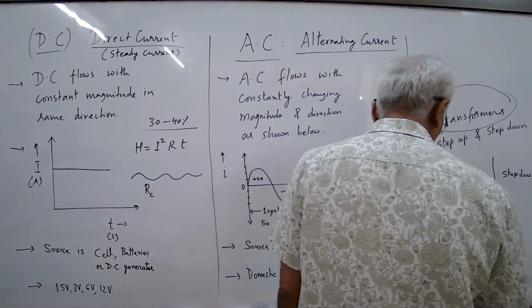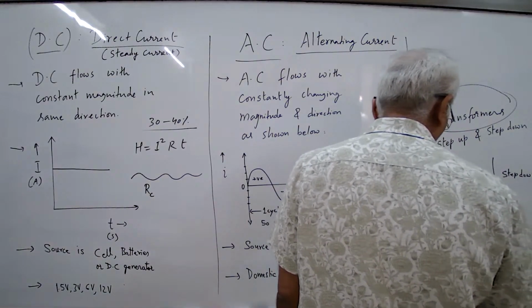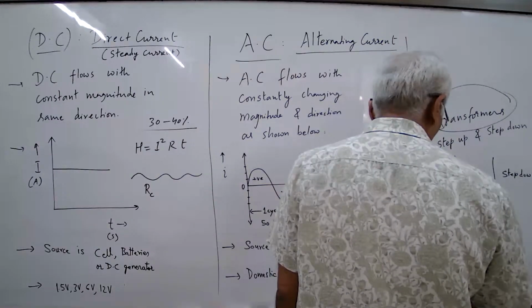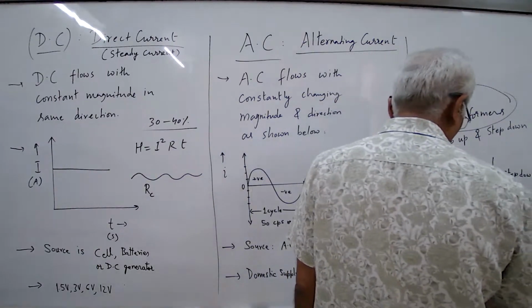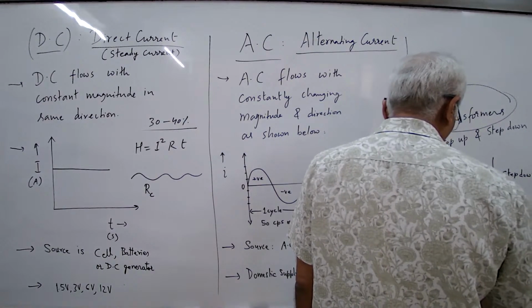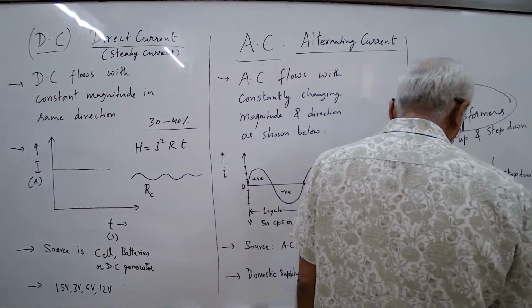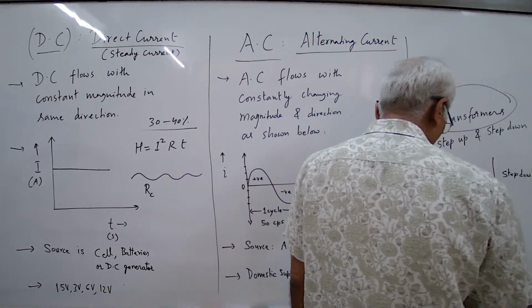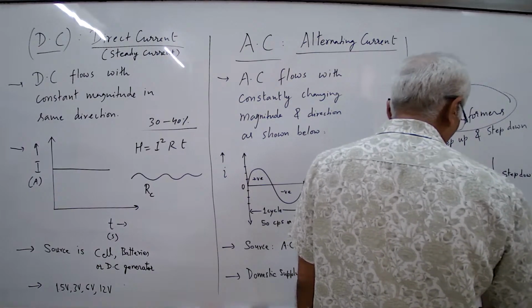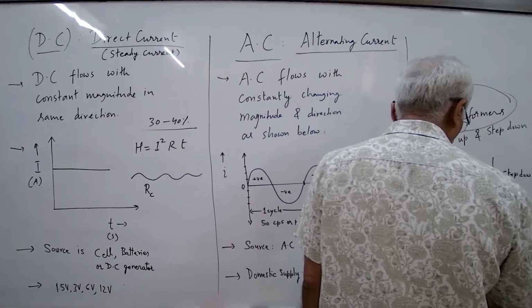Okay? AC is what goes into it. So first AC is converted to DC. So there is one circuit which does AC to DC conversion. Once it is done, DC, then it is also brought down from 220. So both these things are done. It is rectified to DC and it is also brought down to 5 volt to 10 volt.